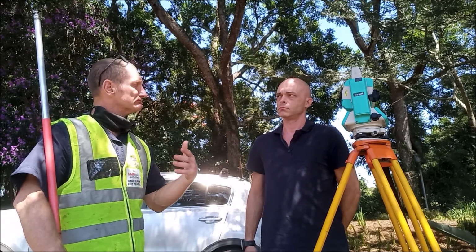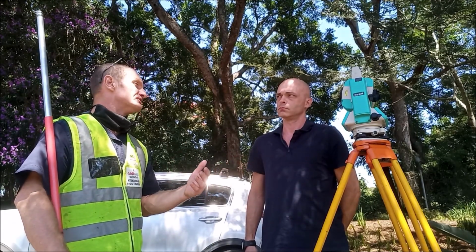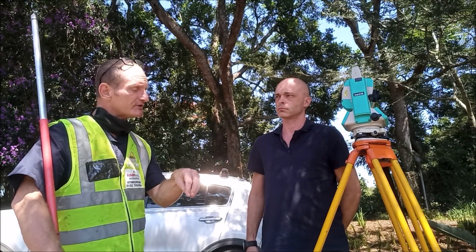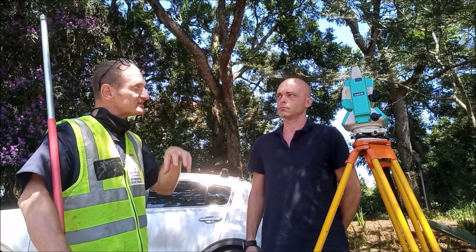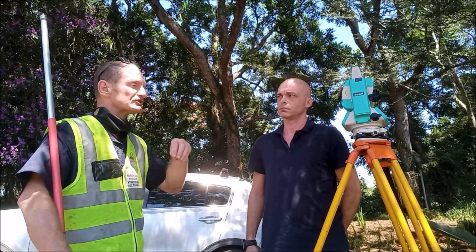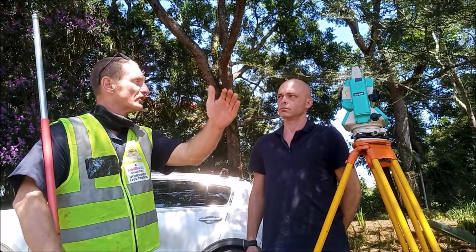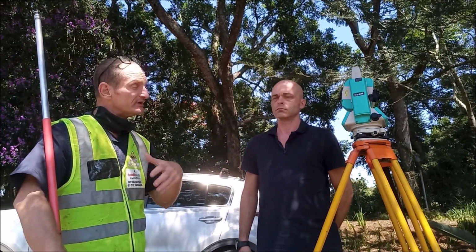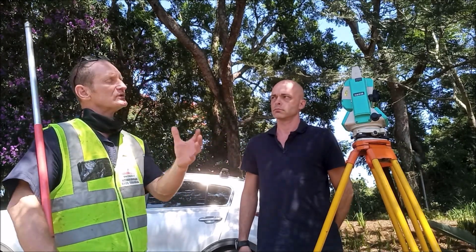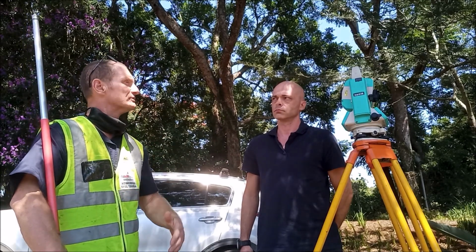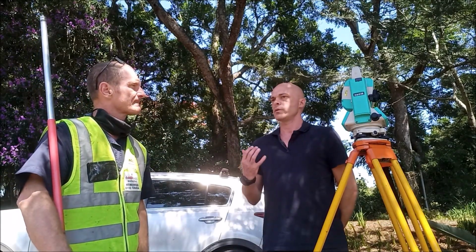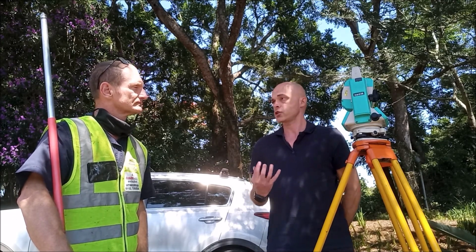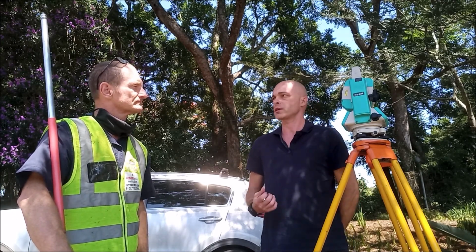By the same methodology, if we're doing a momentum exchange calculation, we would need to know where the point of impact is and where the vehicle has come to rest, the distance that the vehicle has moved, whether that's in a straight line or plotted along an arc. We've used the total station to measure that, and therefore we need to know that those measurements are accurate so that when we apply that to the calculation, we know it's accurate. And obviously, when you're in a court situation, the accuracy of those measurements is quite critical.